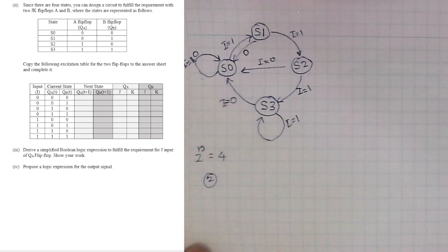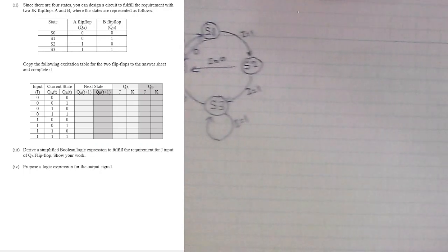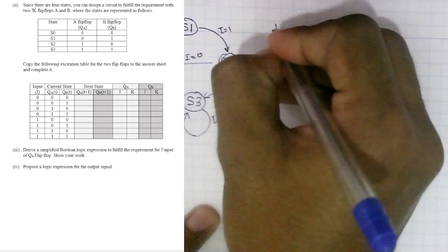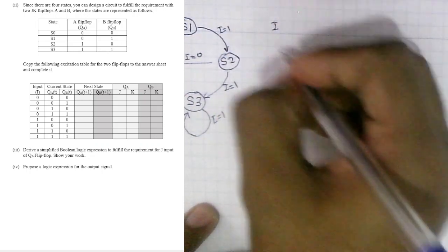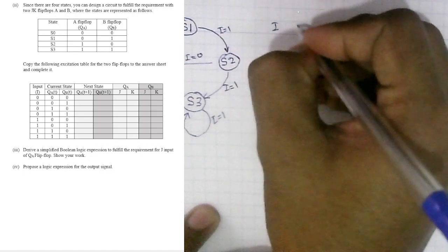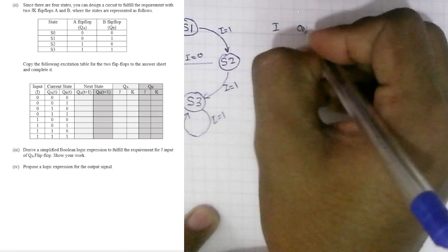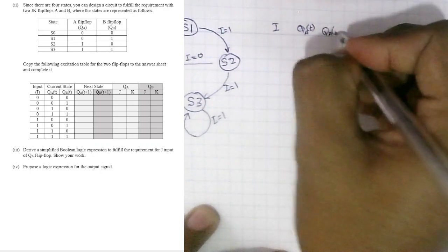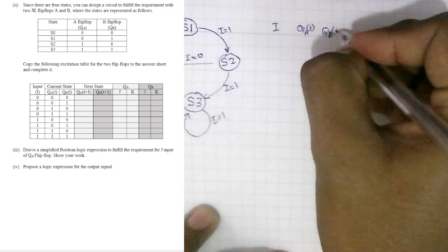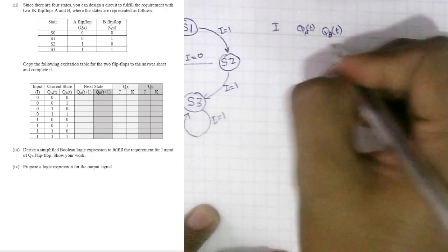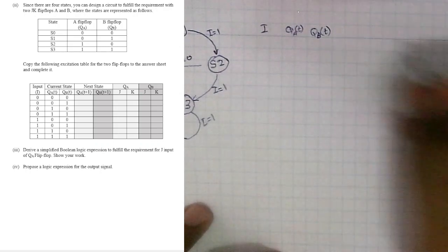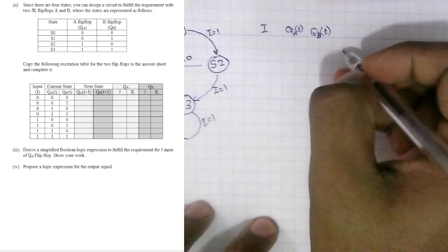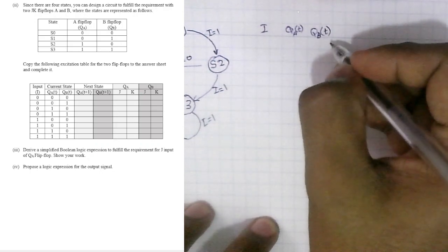for our two flip-flops, right? For that, let's construct this state transition table. We have I, right? And I will go for current states. It will be QA at this level T, right? Then we have QB, right? These are the current state, or at time T, right? Then we have the next state. What we are trying to get for each of these, right?